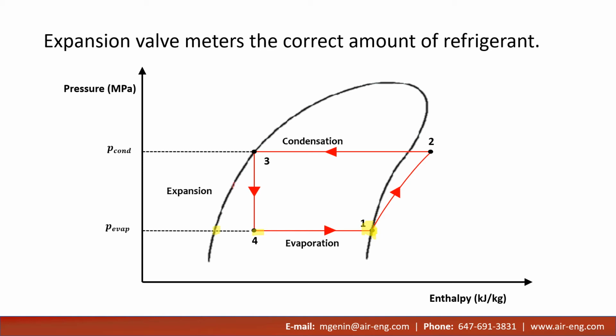So we superheat this refrigerant from a liquid to a gas a couple extra degrees, and that's represented by point 1 prime. As a result, the compressor input power is the same, from point 2 moves over to point 2 prime, because that compressor input remains unchanged.